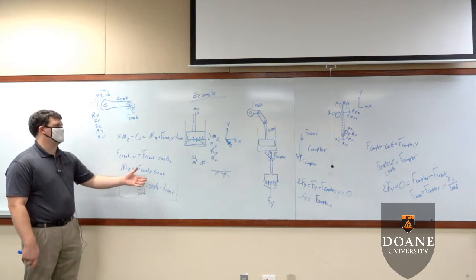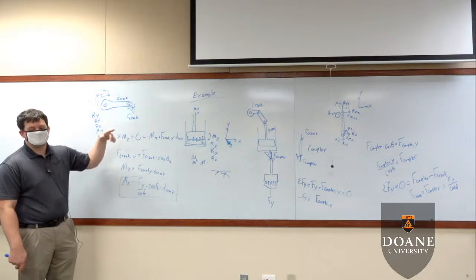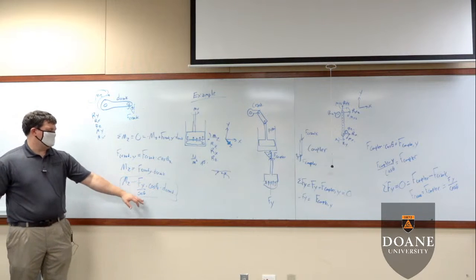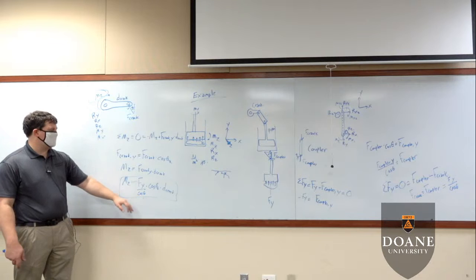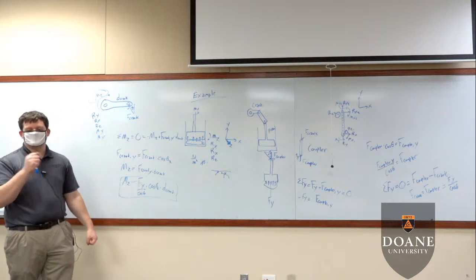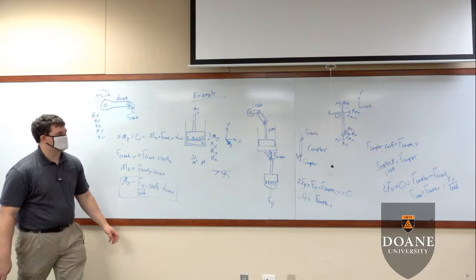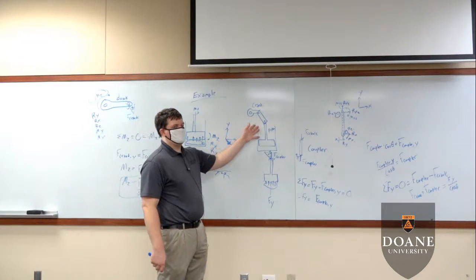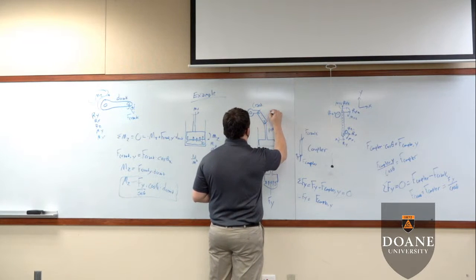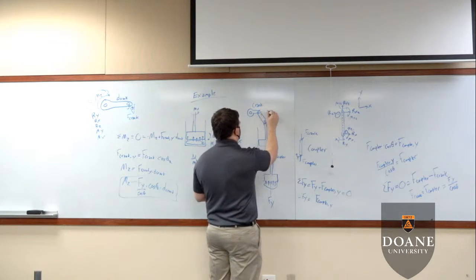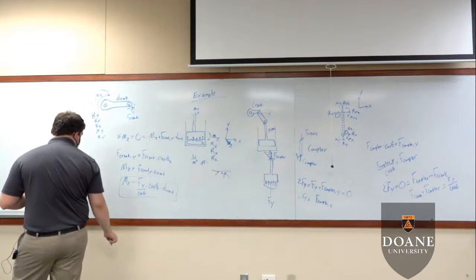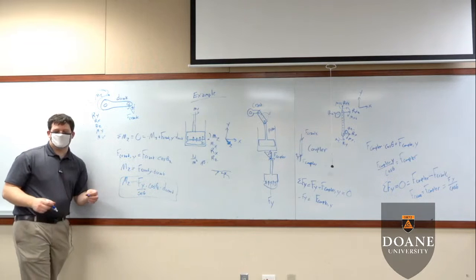Your power transfer is going to occur because your crank is spinning 360 degrees. So looking at MZ, increase the crank value, and try to get theta to be closer to 0 degrees. Try to center that around 0 degrees, which by the way, most people who create pistons will have their coupler go between these two angles because you have maximum power transfer out of that. And then lastly, increase your Fy value.